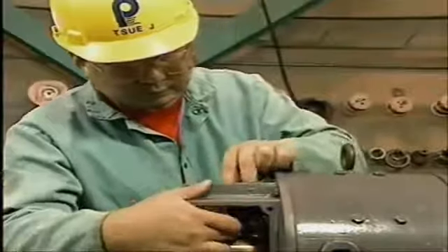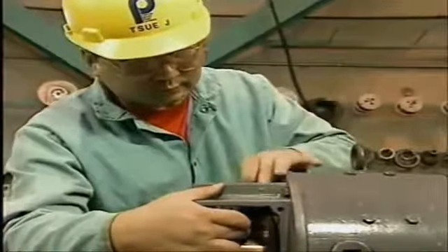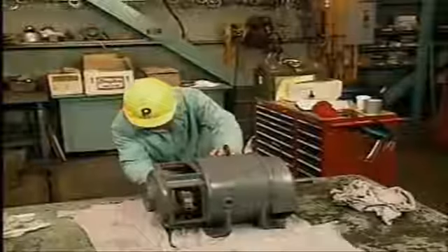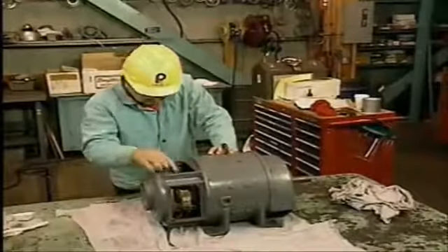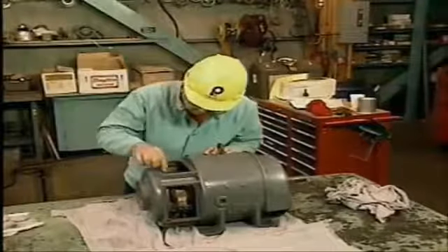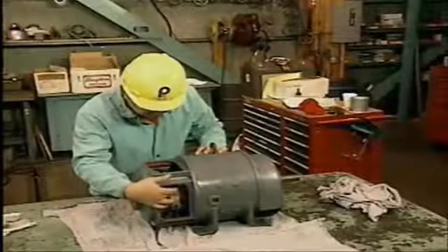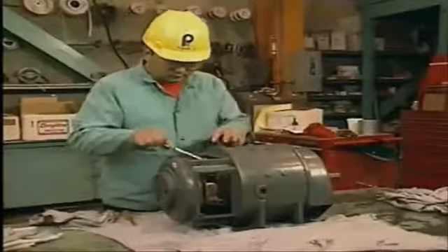The inside surfaces of the brush holders should be checked to make sure that they're clean and smooth. Any burrs or dings must be removed with a file or sandpaper. If they're not removed, a brush could get hung up on them and not make good contact with the commutator. The bottom edges of the brush holders should also be smooth, straight, and free of burrs. If they're not, the edges must be smoothed with a file or sandpaper, or the brush holders must be replaced. Most brush holders can be adjusted, so it's very important to make sure that they're positioned properly. Brush rigging may also need to be adjusted.